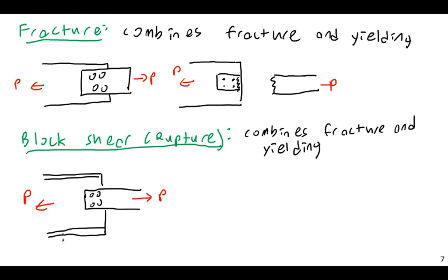In this case, neither this W section nor this plate member is actually going to be pulled into two pieces, or pulled in half. I'm not going to have a break line here, or a break line here. Instead, this smaller member is actually just going to rip a chunk out of the bigger member. Or the opposite could also occur.